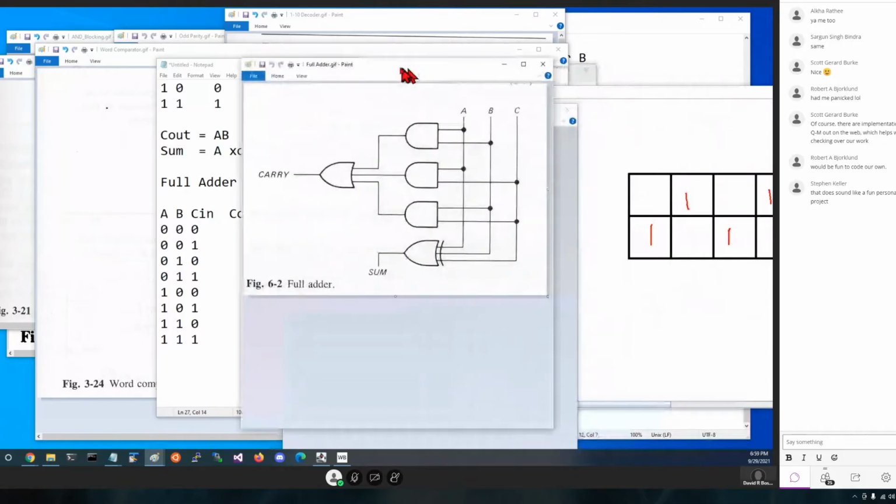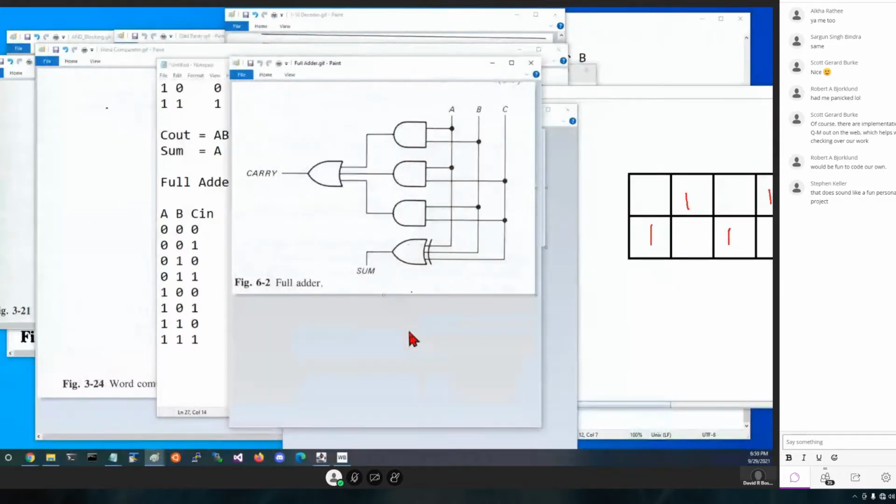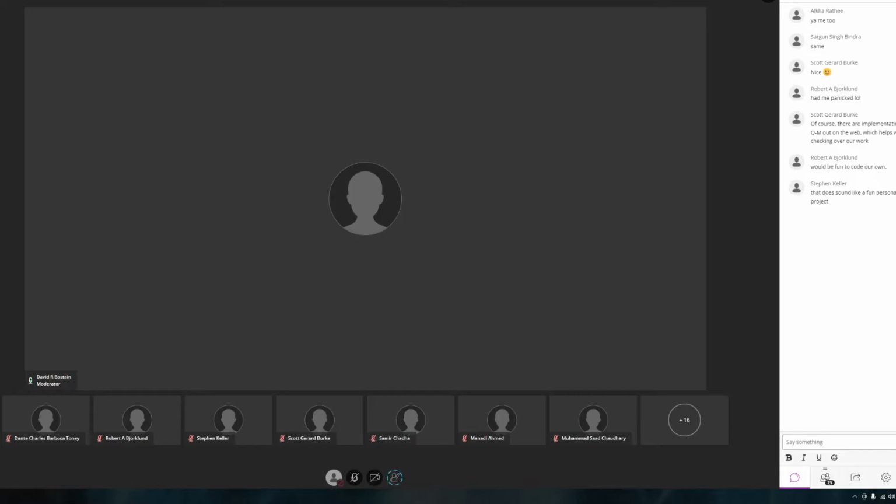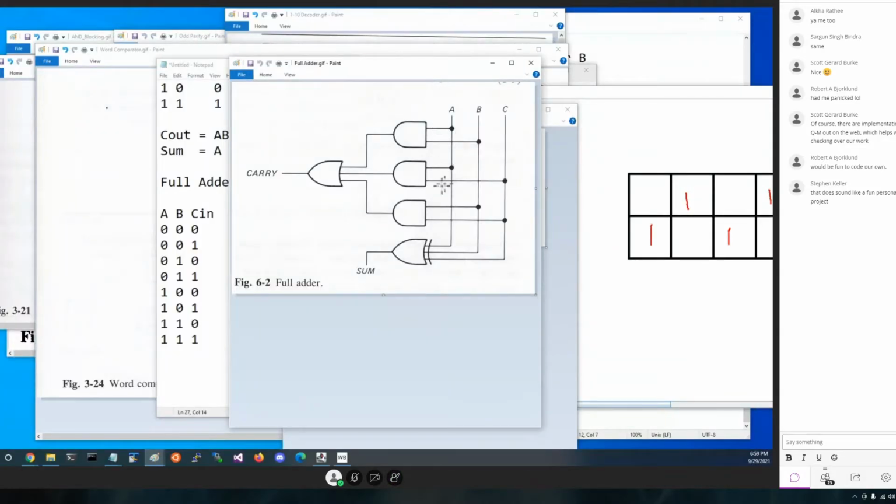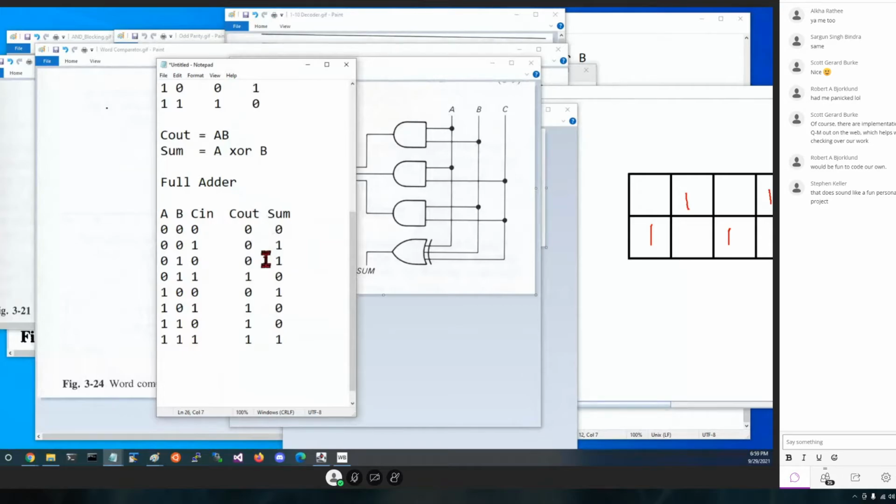A full adder can actually be built this way. One of the things that is a little tricky is that we remember we had A and B, A and C, B and C as our ANDed things to get the carry. And the sum, we said, looking at the table, the top part looks like a XOR. The bottom part looks like a XNOR.